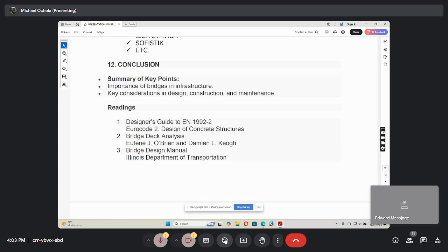I saw you talked about Pakwach. It's a candidate bridge which you could actually look at. My only concern, according to what you're saying, is that the sediments are pushing the bridge, and the bridge has now moved and is disfigured. The expansion joint on the upstream side is widening, while the one on the downstream side is narrowing, which means the section is really moving.